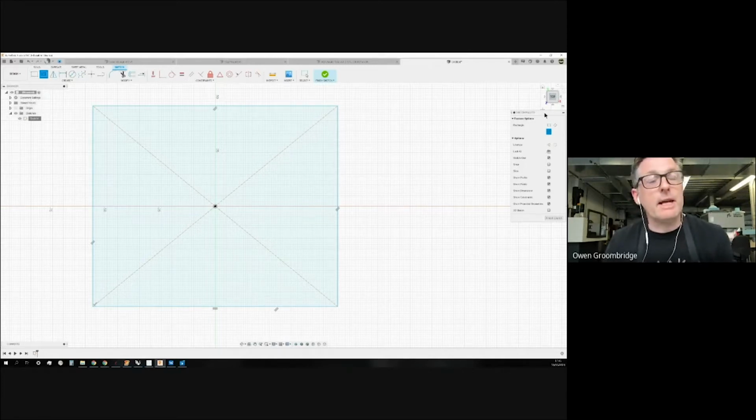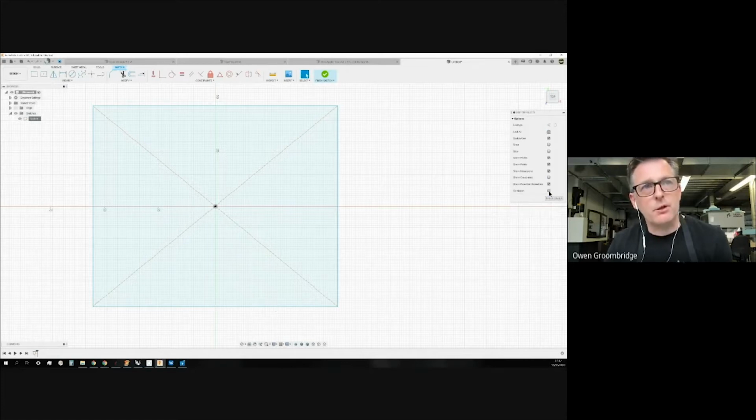You need to find the sketch palette, and the sketch palette might be tucked away, usually beneath the view cube here. It's tucked away to the right, and you can open that up. And this is where Ian showed, like last week, where you can turn things off, like constraints and projected geometries, dimensions, etc. Okay. But here at the top, you've got construction. You can also find center lines as well.